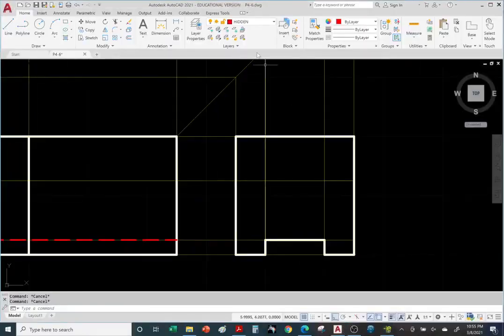Okay, so let's go to the visible object layer. Draw a line going diagonally across from the bottom left corner. Let me turn off ortho. There it is. I've got more freedom, and snap to the upper right corner and right click enter. Okay, so there's our side view. Are we done? Let's go check.